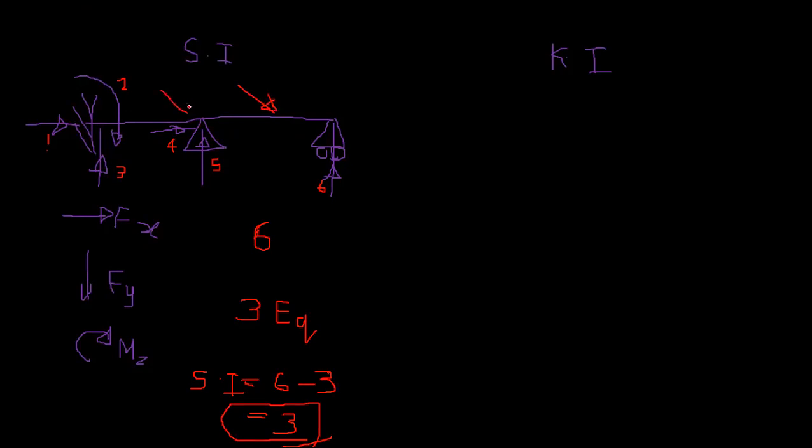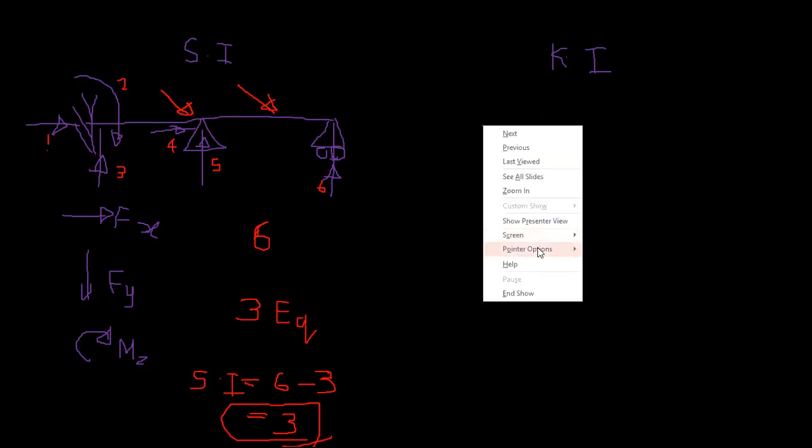If the loading applied is vertical and no horizontal loads are acting, then you probably don't have any horizontal reactions coming into play, and you can't use that equilibrium equation either. So remove that reaction and the equation as well.